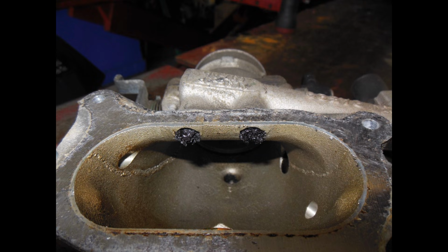Hey, just got back from the new mechanic shop. I found these guys were pretty highly recommended, so I gave them a shot to get this P0401 error solved. We had to conclude, my opinion was that it was either the EGR ports in the throttle body were clogged with carbon, or the new mechanic suggests there's a possibility that the EGR valve wasn't opening far enough. Although typically, I understand that the EGR valves, when they do fail, they'll fail in the closed position. But it was something to consider.